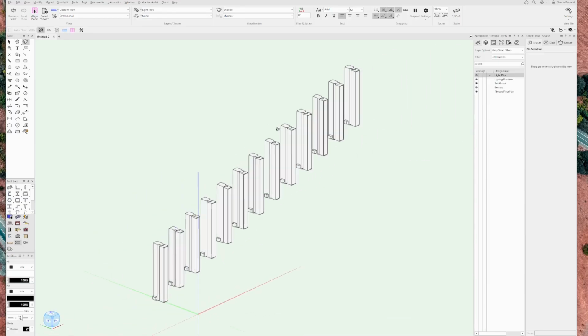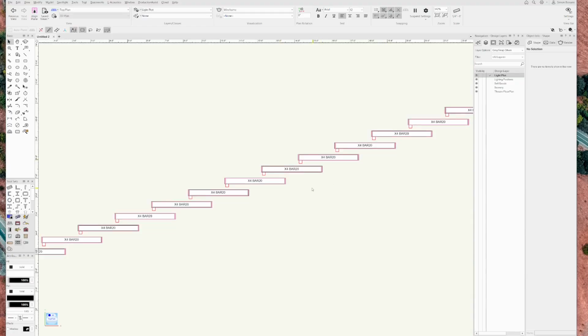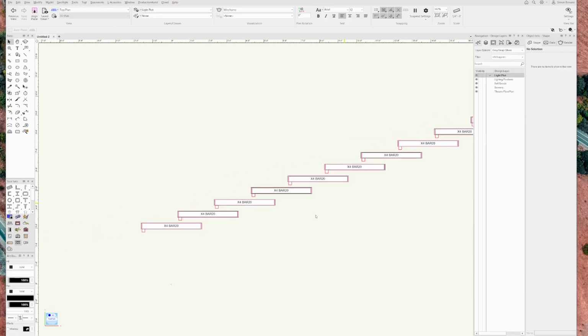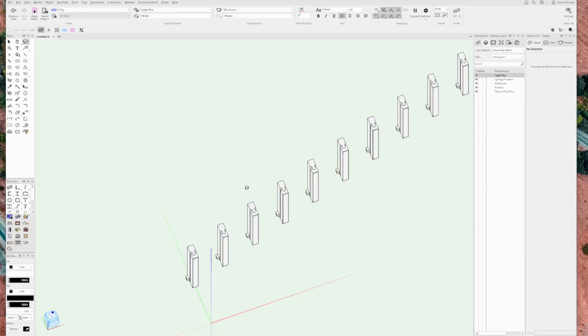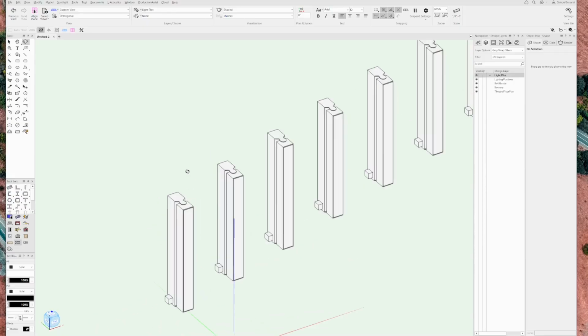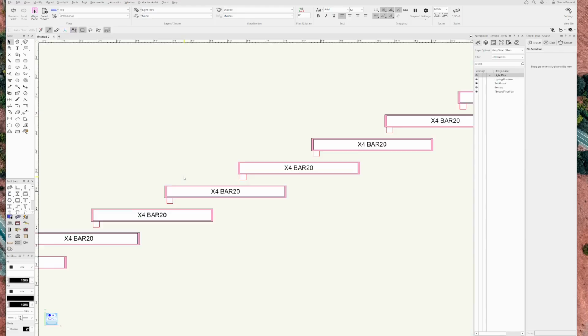The issue is that in the top line view, it does not represent the design at all. It looks like I would want them installed horizontally, which is not what I drew in the 3D. And that's quite normal. That's expected because a 2D, 3D hybrid symbol is connected to a single 2D outline instance. And in this case, it looks like this. So whatever I do with the 3D geometry, it'll always look like this on the top line view.